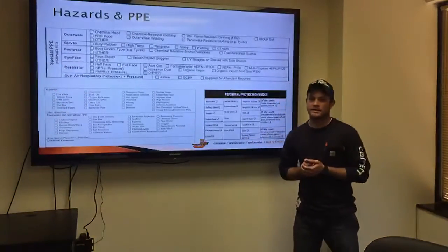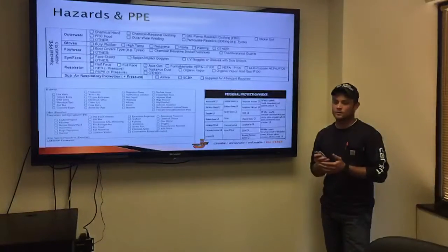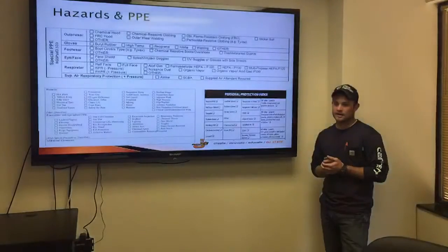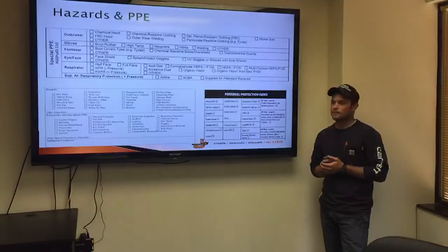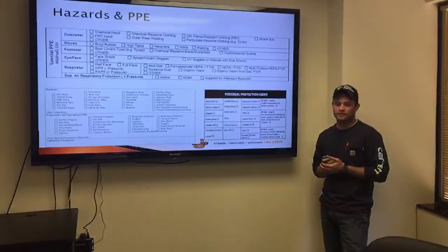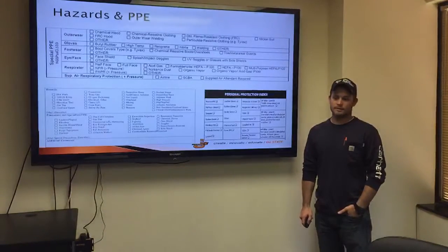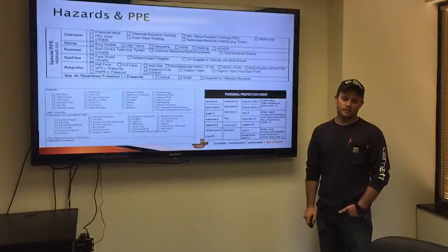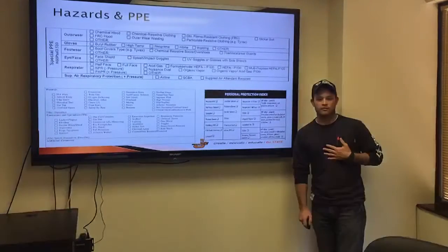Here are my three examples of the permits and their PPE. Basically, OSHA 1910 subpart I is going to be your guidelines on this, and it's going to give mandatory PPE for the oil and gas industry. At least the mandatory PPE is going to be hard hats, eye protection, safety-toed boots, fire retardant clothing like what I'm wearing right now, and a 4-gas monitor.